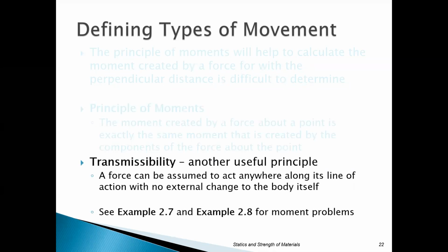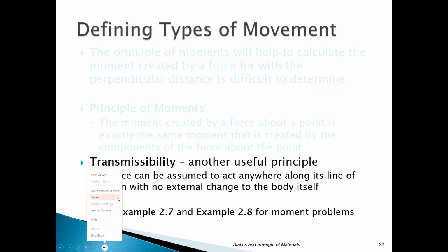The other principle that you can use sometimes is the principle of transmissibility, which says that a force can be assumed to act anywhere along its line of action, and it has the same effect on that body, okay? So I'm going to show you how to use the principle of moments, and we'll get that same answer that we just did, a lot simpler. Okay, so let's go back over. Now again, if you don't understand something, let me know, okay?